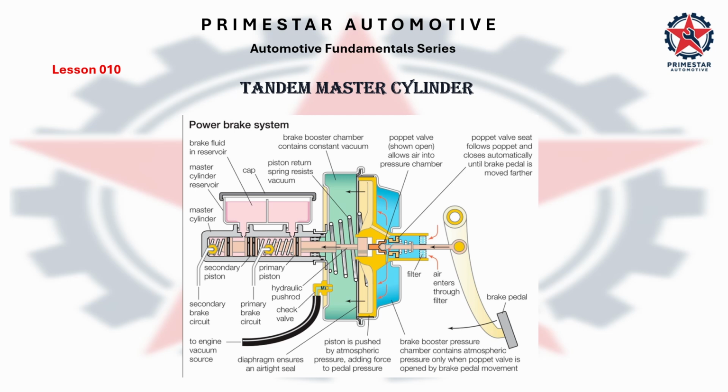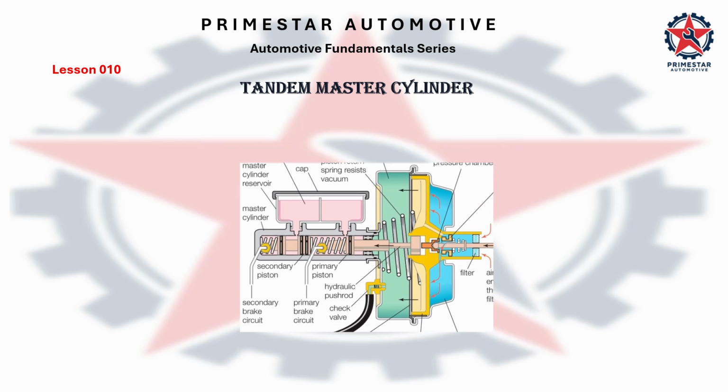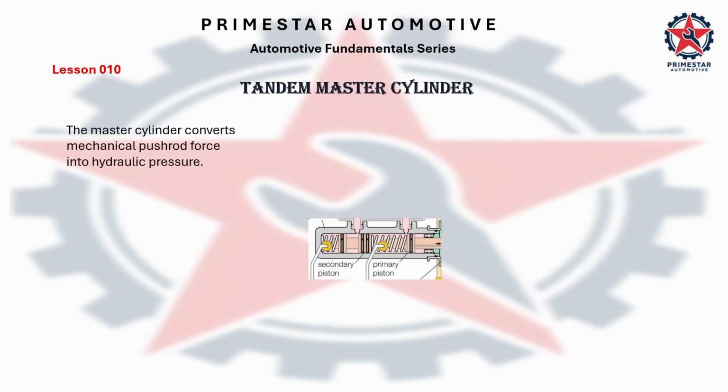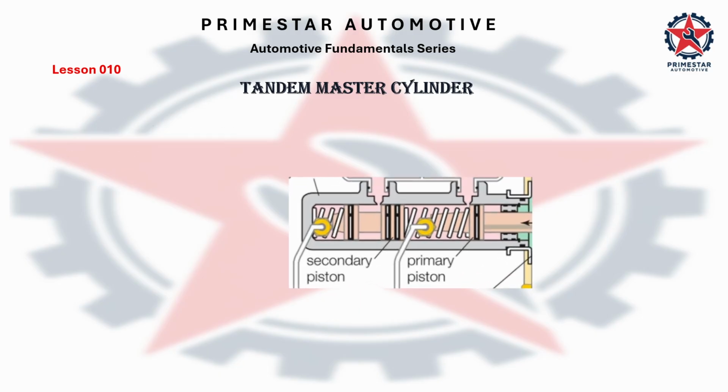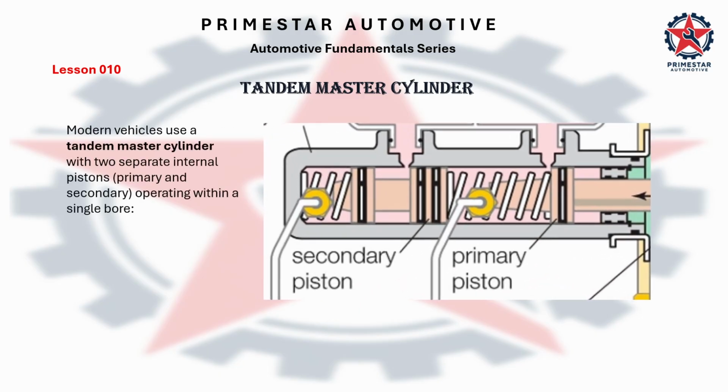Tandem master cylinder. The master cylinder converts mechanical pushrod force into hydraulic pressure. Modern vehicles use a tandem master cylinder with two separate internal pistons, primary and secondary, operating within a single bore.